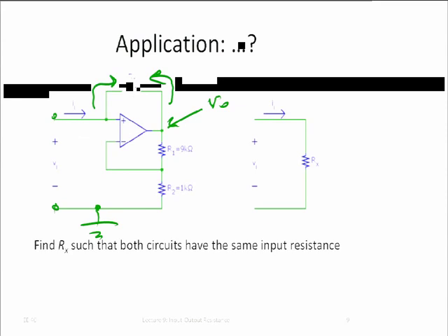Why is it independent? Well, because as we argued, these two currents, these two green arrows here, it really doesn't matter what current flows there. The voltage VI is totally independent of the value of II, because I set it and called that VI. The amplifier at the output is like a voltage source. It dictates what voltage is there, and if it's an ideal operational amplifier, if it has to supply 1,000,000 amps for that, well, the operational amplifier is ideal, it will supply that 1,000,000 amps. It will simply hit the voltage.